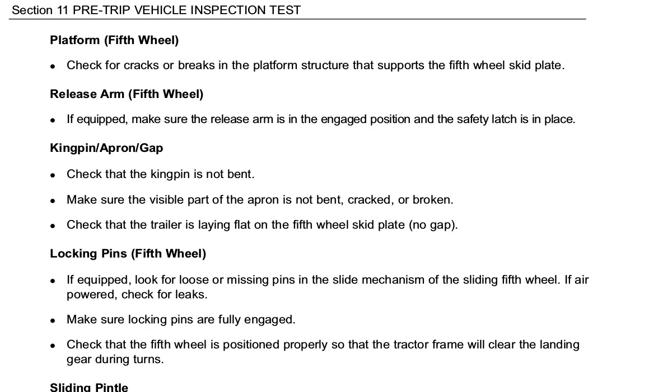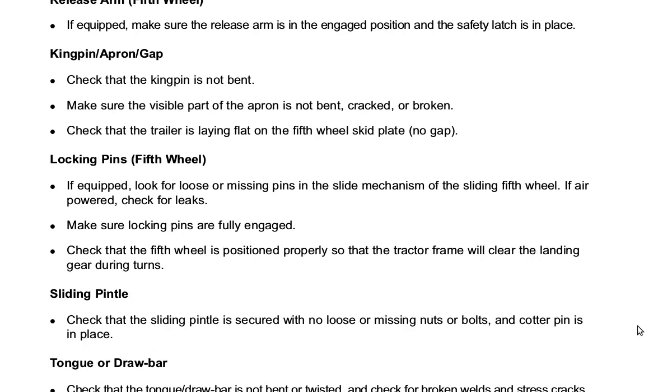Locking pins, fifth wheel. If equipped, look for loose or missing pins in the slide mechanism of the sliding fifth wheel. If air-powered, check for leaks. Make sure locking pins are fully engaged. Check that the fifth wheel is positioned properly so that the tractor frame will clear the landing gear during turns.